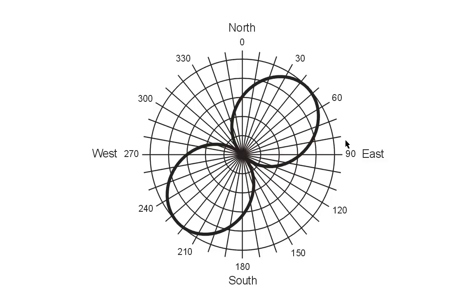What type of antenna of the ones listed, A, B, C, D, or E, can actually exhibit a pattern like this in the horizontal plane? Well, the only one that can is the folded dipole, and that is choice A. If we orient a folded dipole horizontally so that its ends run from northwest to southeast, we will get a radiation pattern that looks like that.